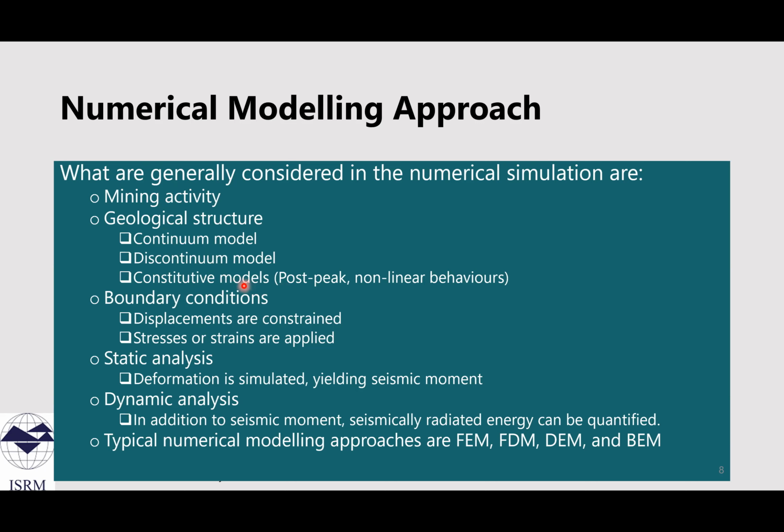So this is another example. In this mine, as I explained, a large seismic event took place in this dike located near this property. In order to evaluate the potential of seismicity, static analysis was performed using this mine-wide model. And here is the result of the analysis. As can be seen, this dike picks up a source state higher than that of the surrounding region because of the high stiffness. This result seems quite reasonable.